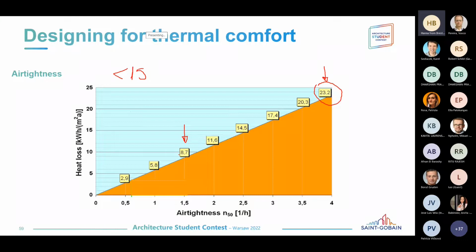You can obtain very tight buildings these days, which basically means that the building was constructed correctly, that when two walls are put together in the case of prefabricated systems, there is no gap, so I will not have drafts in the area. I will not have any pollutants coming inside my construction from outside. And this is a very, very good way of checking the quality of the construction itself. It helps within the designing, it helps within the construction stage, and it can be done in several steps. And I think the majority of the European states have these airtightness measurements in the thermal regulation.